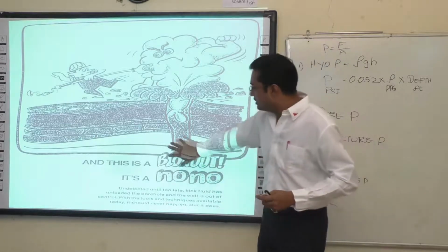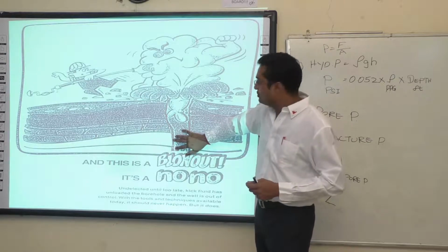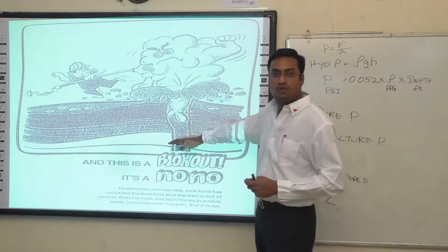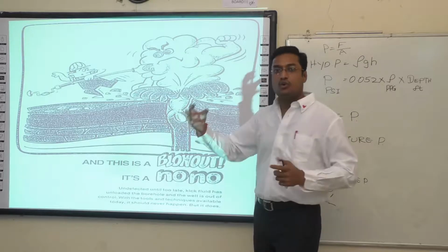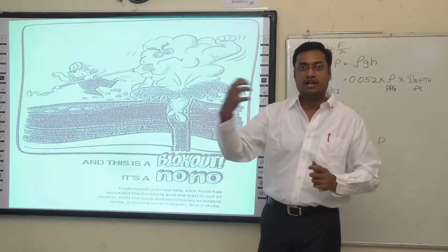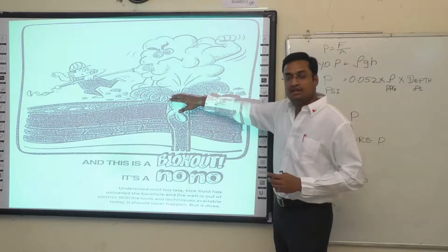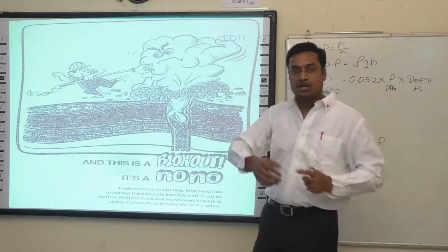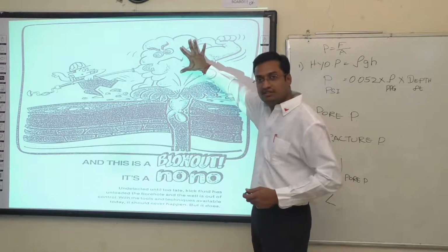The kick is not going to stay there. Once it enters the wellbore, it's going to start coming out of the well. It's going to move up. And when that formation fluid, the unwanted entry of formation fluid, reaches the surface, it is uncontrollable because it has grown bigger in size.